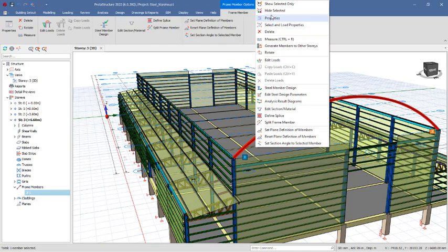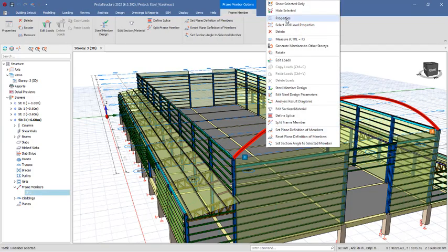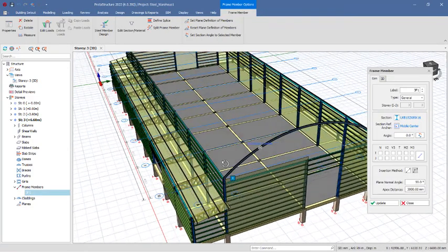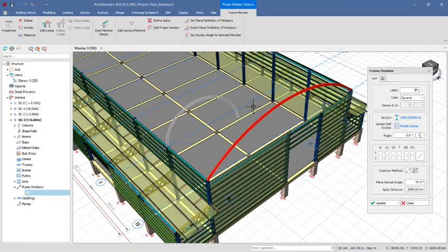Okay, I'm not seeing any copy options here for this. Since there's no copy option, we could have copy and then populate it along these directions. So we click on this, right click and click on properties, and we are going to be using this property to place this curve beam rafter on other positions.